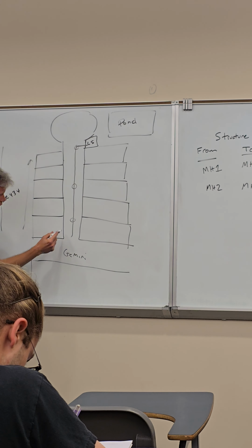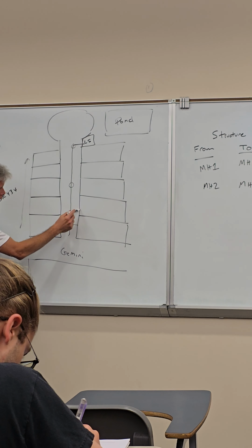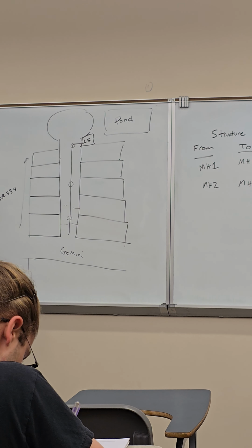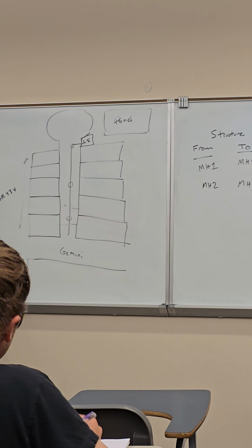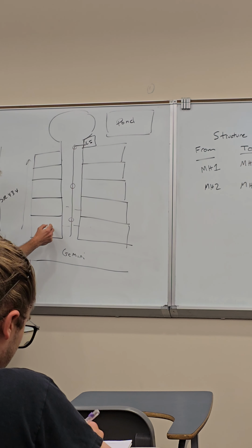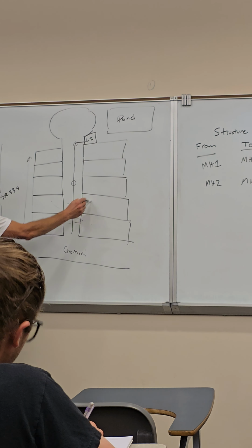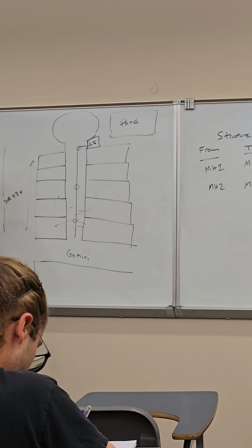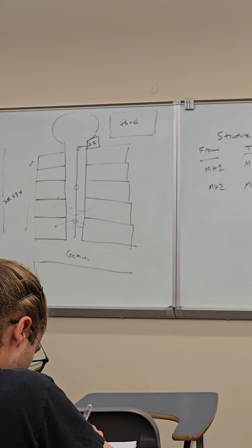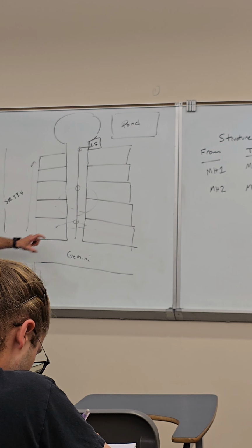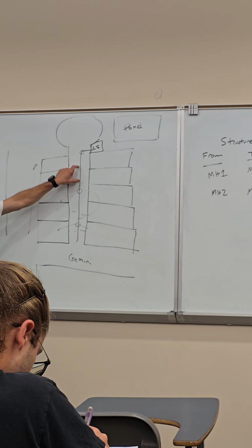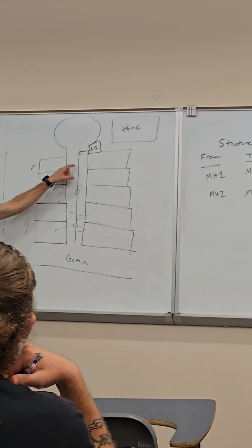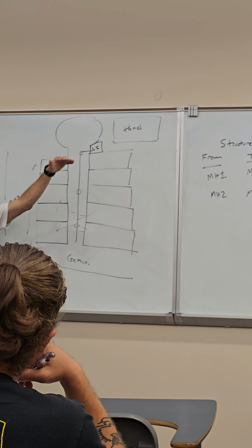And I recognize each of these would have a separate lateral, but we're just gonna make the assumption that these 2 lots go to this manhole, maybe these 4 lots go to that manhole, these 4 lots go to that manhole, okay? So the goal is you want to be able to calculate the flow in each of these pipe segments as you're going towards the lift station.